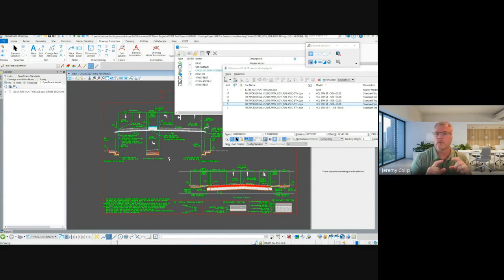Those materials are assigned to the components of your corridor model. So when I display a cross section, I can display it with those materials turned on so that they give me basically the same view of where I get my aggregates, my pavement, whether it's concrete or HMA, grass, or rock mulch. Those will show up in that, so I don't have to do the materials separately. Right now, we're doing the materials separately just for visual purposes and to relate back and forth to the pay items.